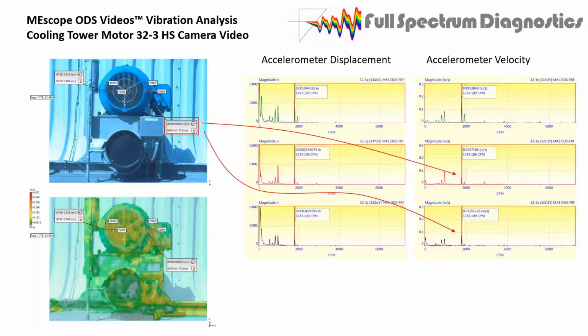So if you can zoom in and get multiple panels on the object of interest, that'll help a lot. I just listed off all the phase-related problems. The cell phone frequency range, the frames per second, giving you an F max of about 120, is going to capture most of those phase-related problems. Looseness, misalignment, bent shafts, cocked bearings, unbalance, and so forth.